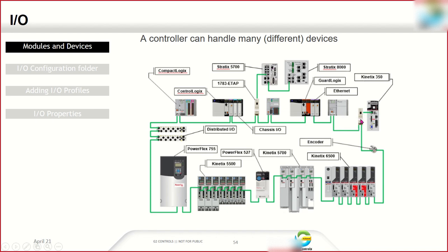Here is again the ETF to take out the connection to an external device. Kinetix 350 is the servo drive. These are the servo drives, Kinetix 5500. This encoder also has two Ethernet ports. All devices have dual channel Ethernet ports. Why is it required? Because all devices are DLR compatible. For DLR we need two Ethernet ports.